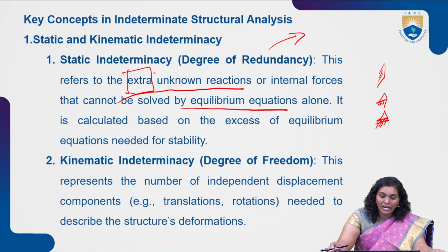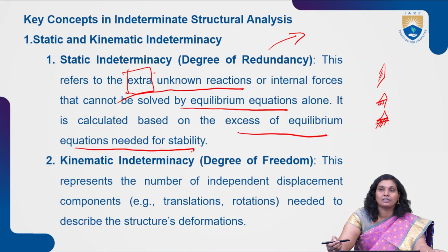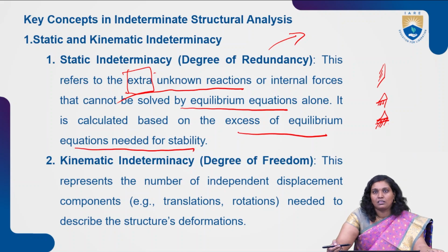It is calculated based on the excess of unknowns over the equilibrium equations needed for stability. That is the static indeterminacy or degree of redundancy.